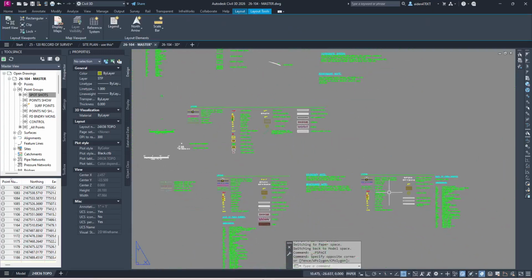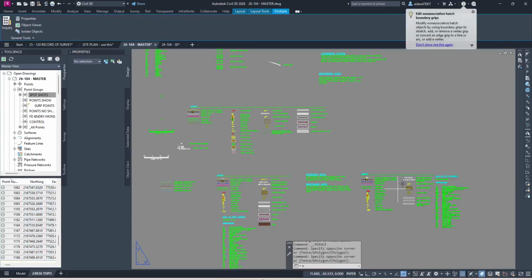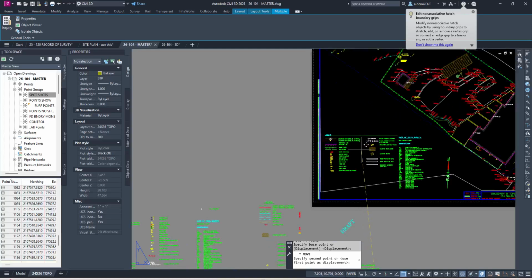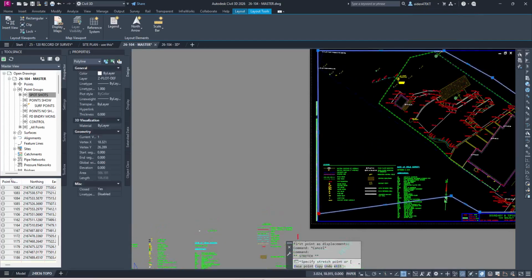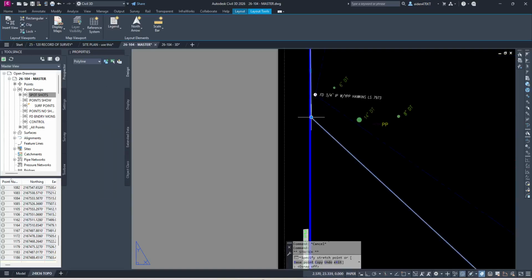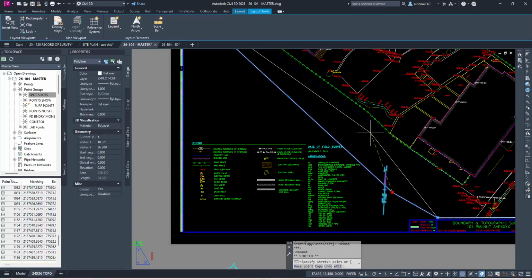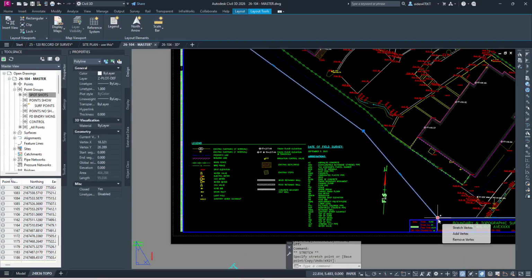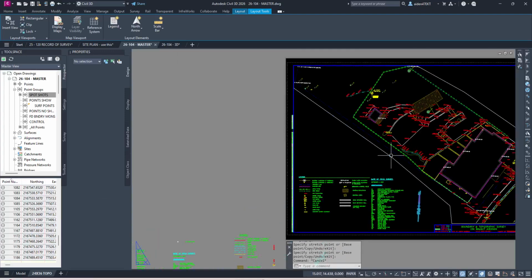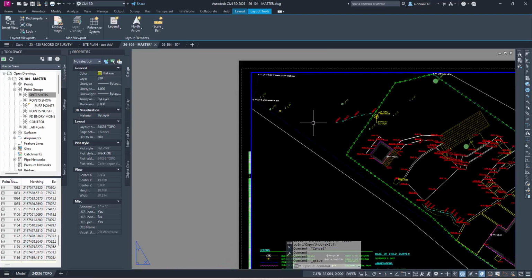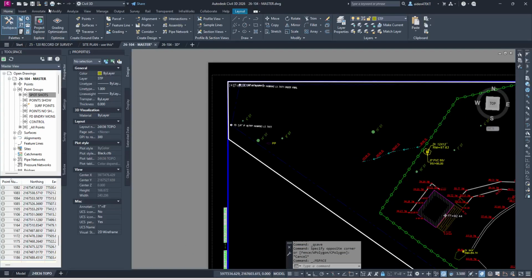And then put in the title block here, whatever you have room for. Looks like we have room here. Put this whole block. Now I'm actually going to move my polygonal viewport out of here. I like to have a nice border like that. It gives me, just mentally, a clear break there. Alright. So then don't forget to label the boundary line.